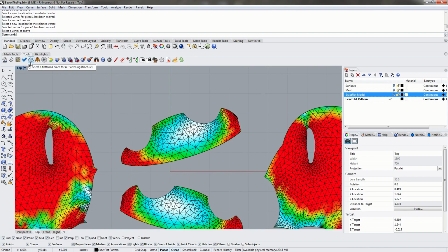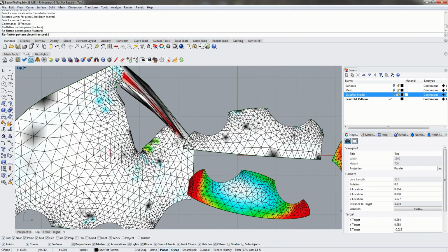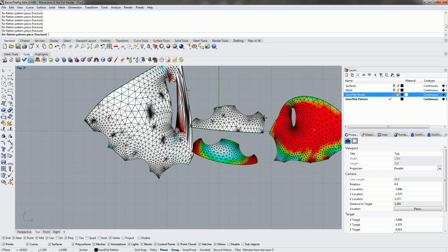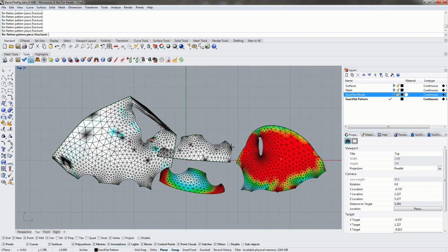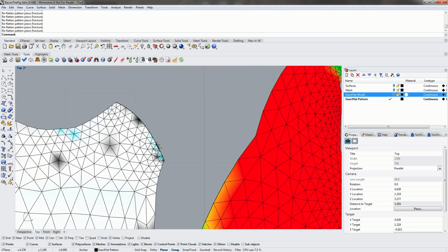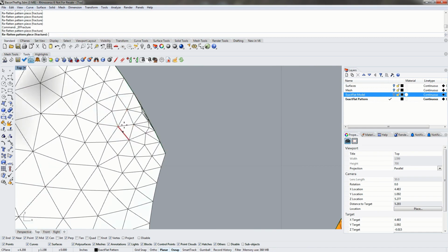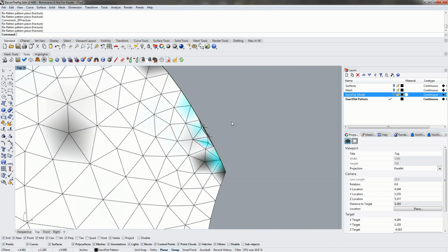Lastly, if we have a mesh, I'm going to try to create a bad mesh using the fracture tool here. If we've got a mesh that none of the tools are working to try to remove the flip triangles or the folds or wrinkles, we'll use this one as an example over here. We can see we've got some flip triangles right here. We can use the ExactFlat cutting tools to cut out, whoops, I just accidentally fractured that. So I'm just going to fracture this again. So we've got our flip triangles back over here.